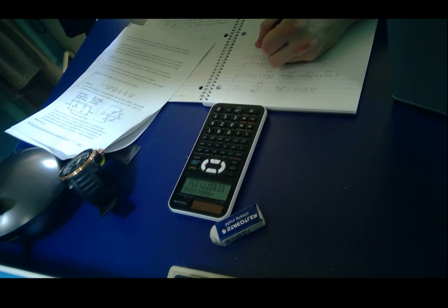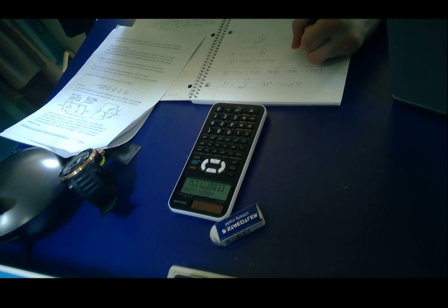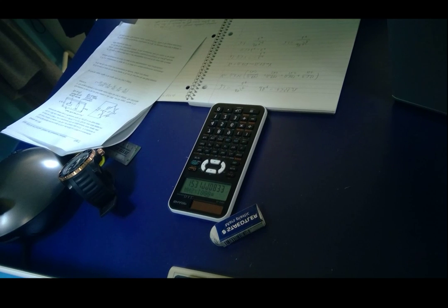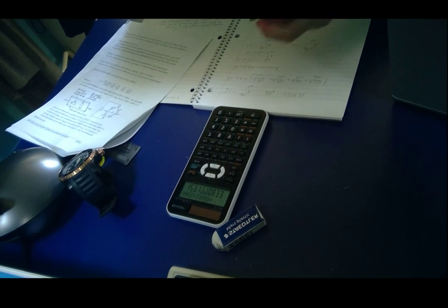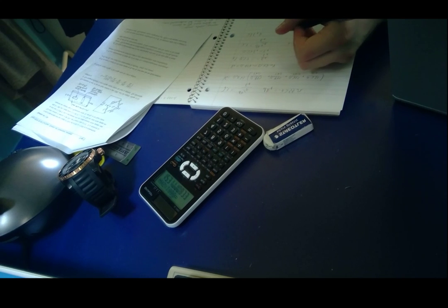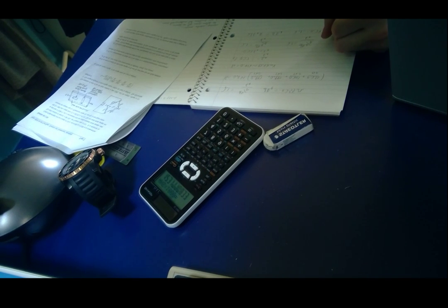So 2.1 is equal to dR axial divided by R divided by the axial strain, and 2.1 is also equal to dR transverse divided by R divided by the transverse strain. All right, so now we just relate these quantities together. So 2.1 epsilon a R is going to be equal to dR axial, and 2.1 times minus 0.27 epsilon a times R is going to be equal to dR transverse.